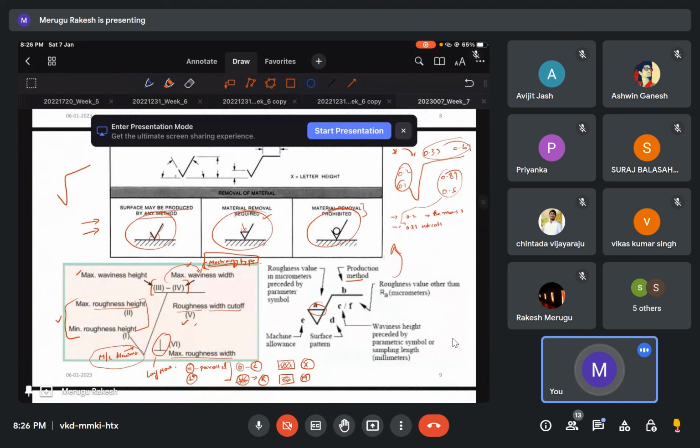So it depends on the usability. The spirit level is something I can take anywhere, literally, and measure. But the autocollimator setup, I cannot take everywhere. The spirit level has to do with macro, bigger length scales, whereas the autocollimator is related to much smaller scales. The autocollimator is for examining the surface at a micro level, whereas the spirit level is a broad level, you can say.